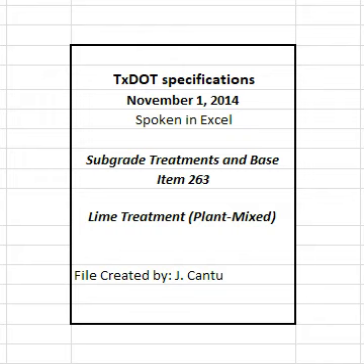4.1 Mixing. Thoroughly mix materials in the proportions designated on the mix design, in a plant that meets the requirements of Section 263.3.2, Mixing plant. Mix at optimum moisture content, unless otherwise directed, until a homogeneous mixture is obtained. 4.2 Placing. Place lime-treated base on a subgrade or base prepared in accordance with details shown on the plans. Bring the prepared roadway to the moisture content directed.